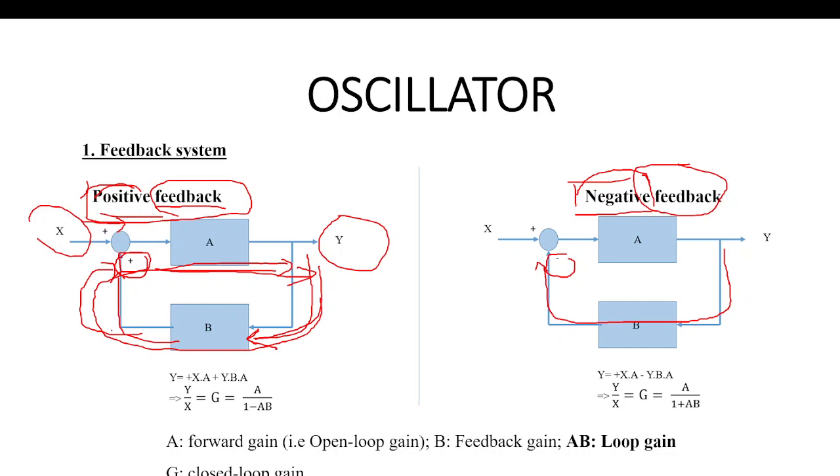After we understand the concept of the block diagram representing a positive feedback and a negative feedback, we need to define the transfer function of the block diagram. When we talk about the transfer function of the block diagram, we consider the output signal over the input signal. Let's look at, for example, the positive feedback here. First, we consider the input signal. Please pay attention to the arrow direction. They are very important when you're deriving the transfer function of an abstract block diagram of a circuit.